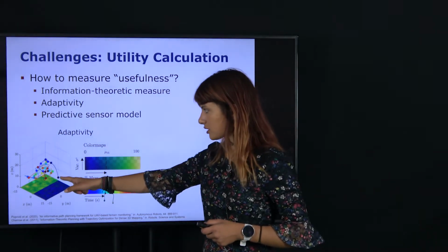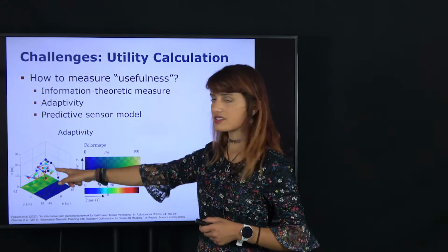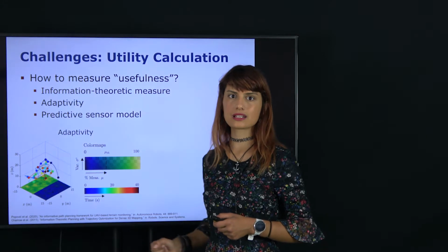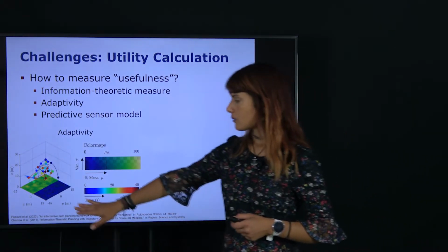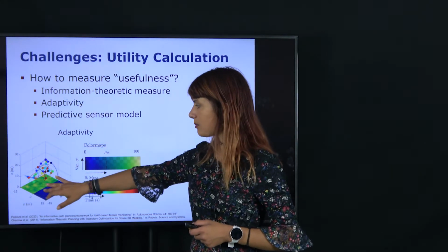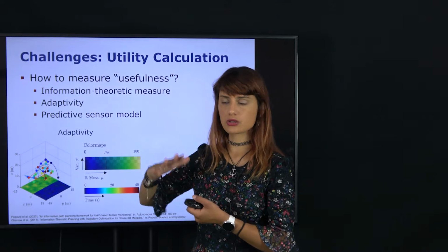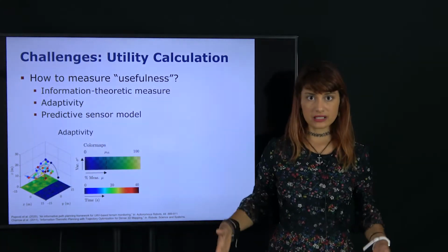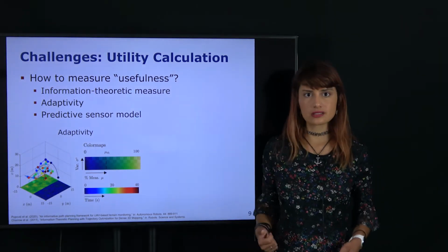The dots here show the locations that the UAV took measurements at, whereas the line shows its travel trajectory using an informative planning approach. And on the bottom, we can see a very binary type of terrain landscape that it is monitoring from a top-down view. At each of these measurements, the camera on board the UAV registers the image and fuses it into the map.